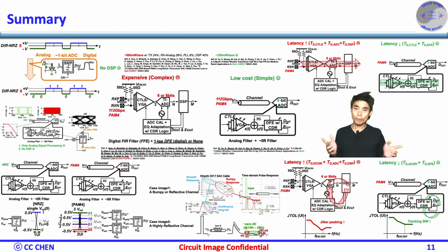Second, low power. The analog PAM4 RX can achieve lower power with a reasonable SNR than the DSP-based PAM4 RX because both high-speed ADCs and complex DSP are not needed. Third, a simple 2-bit ADC reduces both the analog and digital complexity a lot, and the area is much smaller than the DSP-based PAM4 RX.